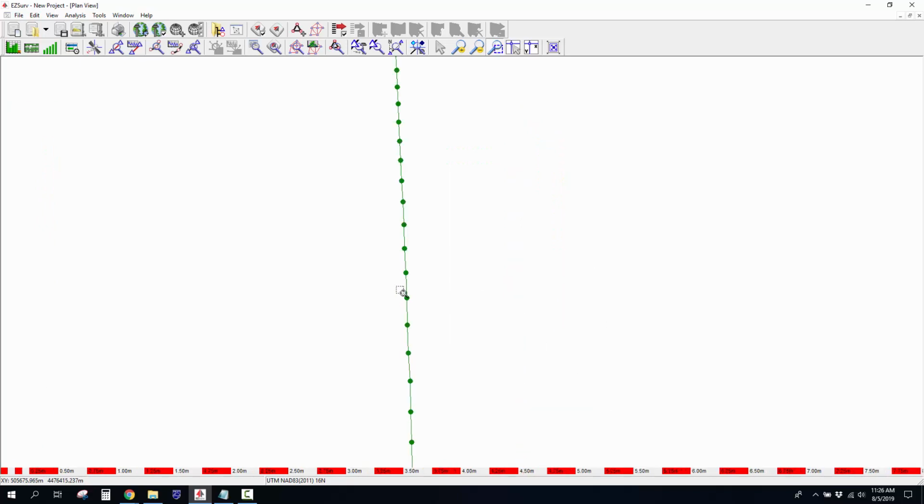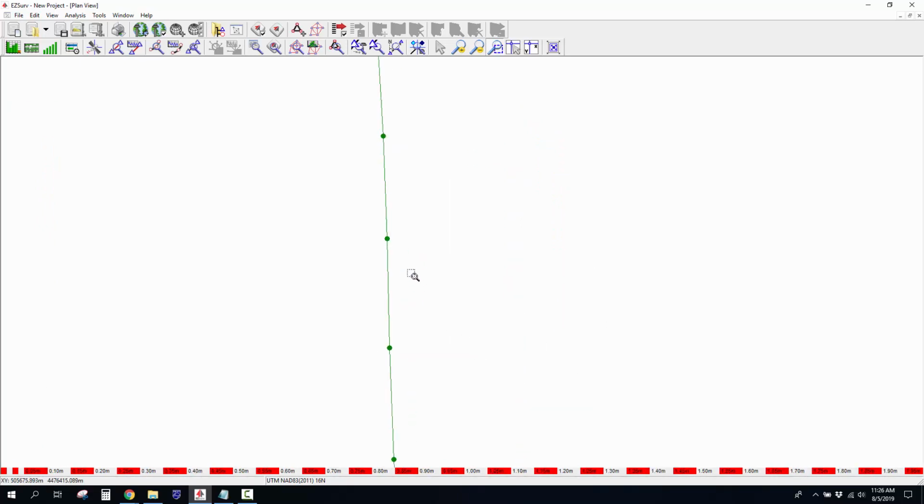The next step that we want to take is to interpolate these positions to where the actual images were captured. So in the event log, we have precise time data so that we can know where along this line each individual photo was captured.